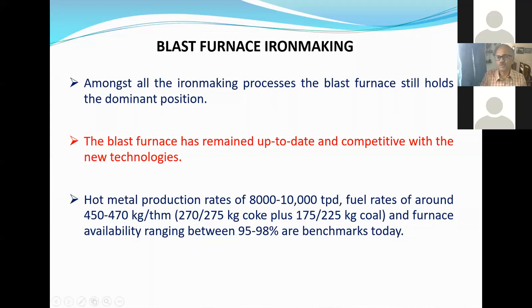Because you have to supply a minimum amount of coke into the blast furnace, because coke has a great role to play. Not only can you supplement its heat generation and its reduction potential, but you cannot replace one of the major properties of the coke, that is to withhold the overburden. In the lower part of the blast furnace, everything is liquid except the coke, and coke remains in the form of dead man coke, and that basically holds the overburden. Also, that dead man coke carbonizes the liquid iron and gives a very porous bed for the liquid to come down to the hearth. So dead man coke is very important.